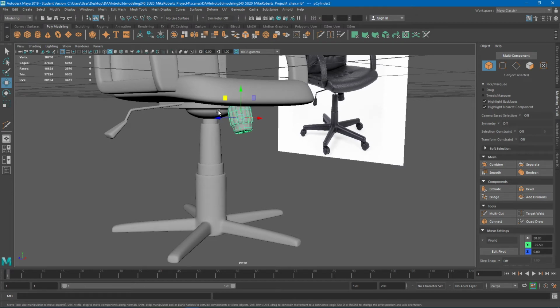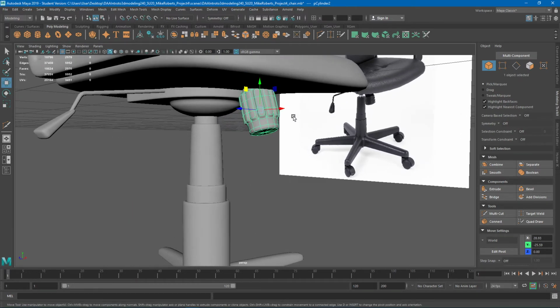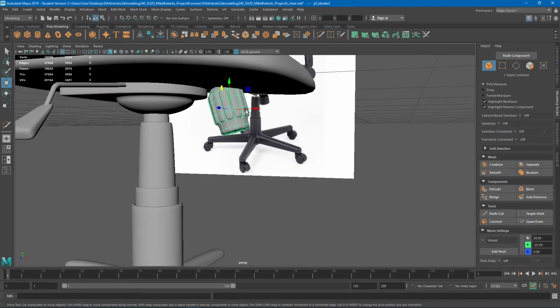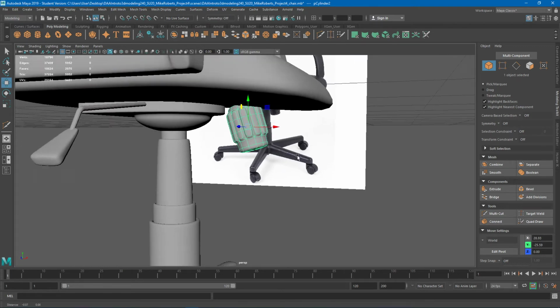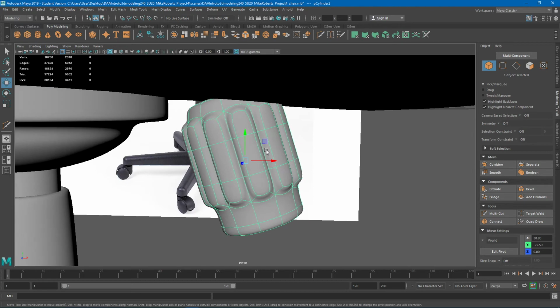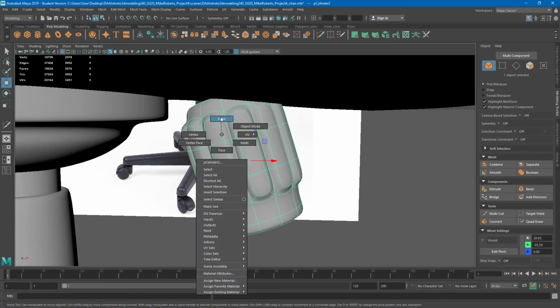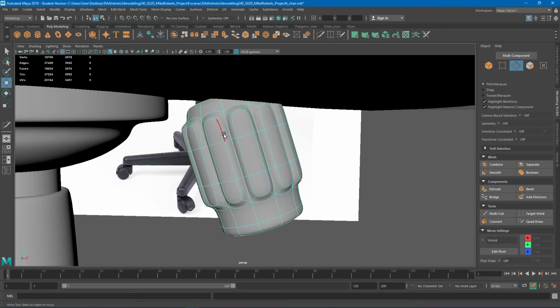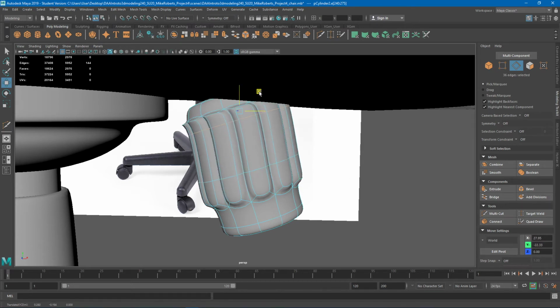So those were nice to get the little quick reminders of, hey, extrude, right? Keep faces together off. And I remember I did these without these edge loops in them. I kept them as a single face here so that keep faces together would work well for those. Because I knew later on I could come in here and add the extra edge loops, right? To sharpen the shape up a bit. And if you wanted to adjust this even more, right? Like right here, so if I go to edge mode, right? Hold down right mouse button over edge, double click on an edge loop. If I just try to move this, right, it's not really going to work great.